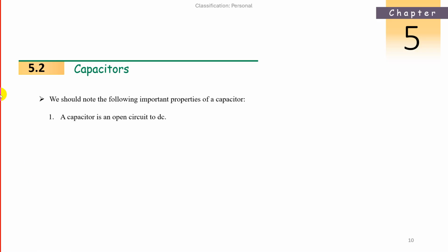It will store and will give back. Both possibilities are there. So a capacitor is an open circuit to DC. The voltage on a capacitor cannot change abruptly. The voltage on a capacitor, we cannot change instantly. It will take some time.